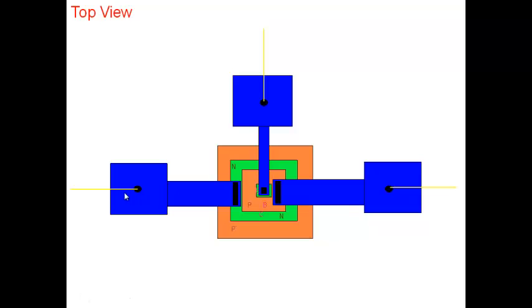So the actual transistor is a small, tiny chip of silicon, to which there are metal pads making contacts to the different regions of the transistor. To these pads, there are very fine metal wires. Then they make a contact to the terminal. That's how a packaged transistor may look.